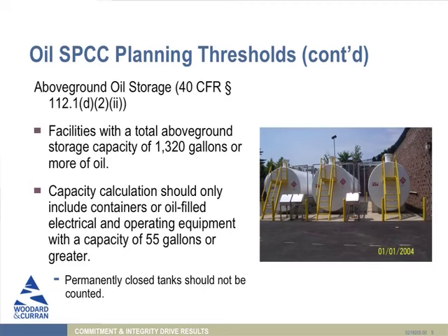The easier thing is to put those drums on a spill pallet or provide some other secondary containment for them. We'll talk more about that in a moment. But typically, if these are just being used for their function as wastewater treatment systems, they're not covered under the SPCC rules.